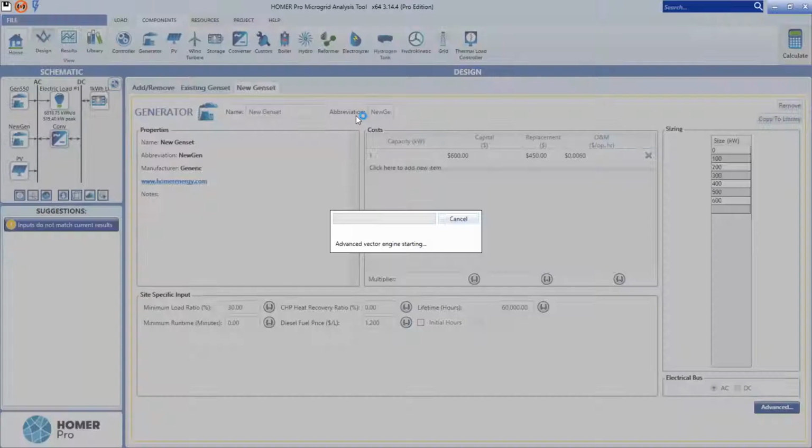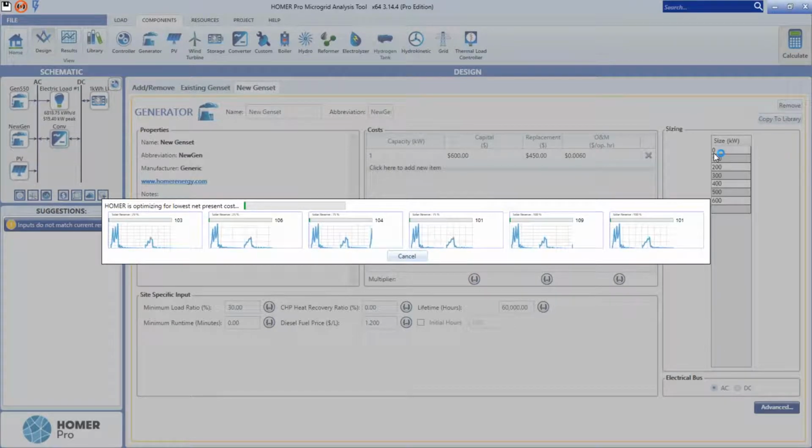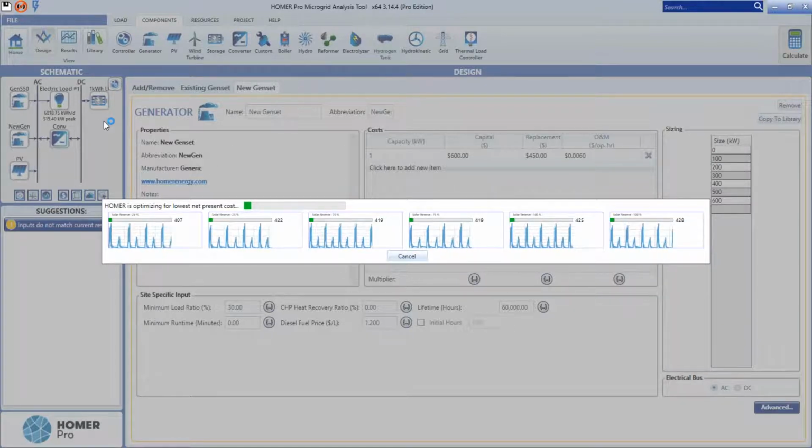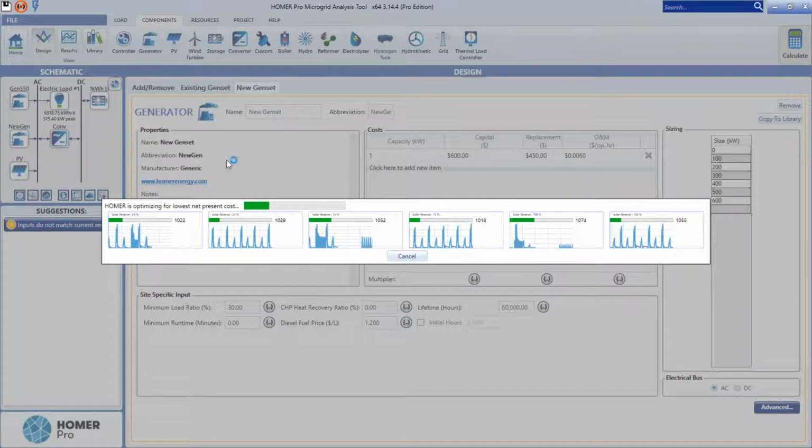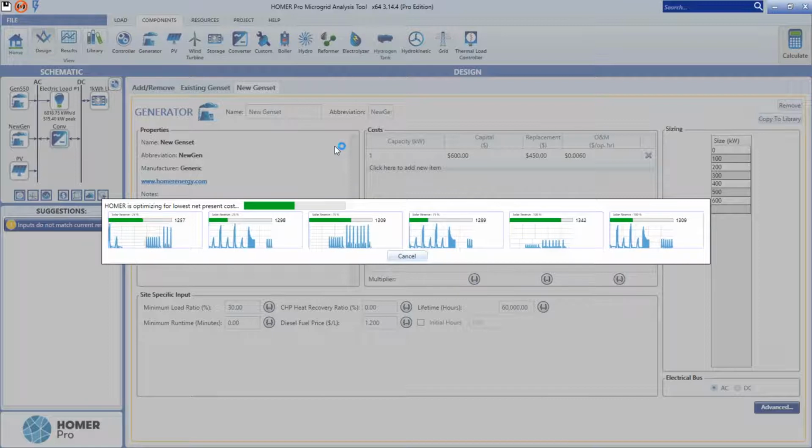Okay, we're deviating a bit from our configuration, but I want to emphasize the 0 point here on the sizing, so that we will have a choice of not using any genset and what will be its impact to a standalone system, because we already have the battery, as was earlier raised in a question, as a grid forming device that our AC PV system can ride on. So this also gives us an option for zeroing our fuel cost, but look into the capacity requirement of the system. So it may require a lot of capacity if we have a large requirement on reserve, especially on the solar. Okay, so this will be the last exercise before we go into multiple gensets.